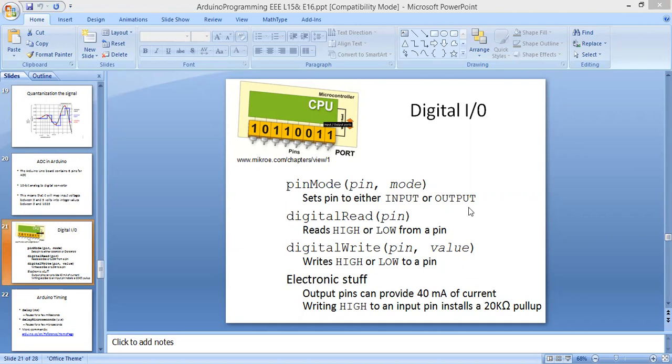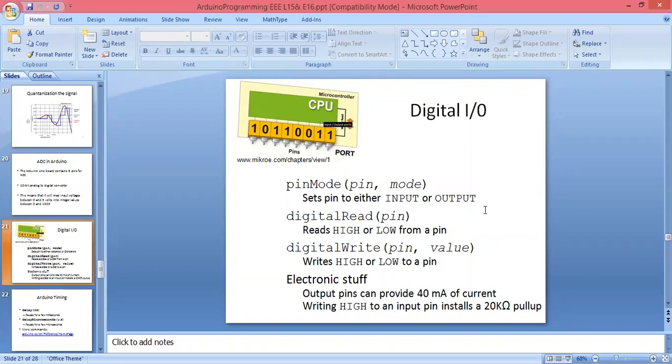Okay. So you can see here, when we have to assign any pin as input or output, we can assign it by using the pinMode instruction. If we are taking any value, we can say we are reading the value. If we are receiving, at that time we can receive that value by using digitalRead. And if we are giving data to the Arduino board, at that time we can use the digitalWrite instruction.